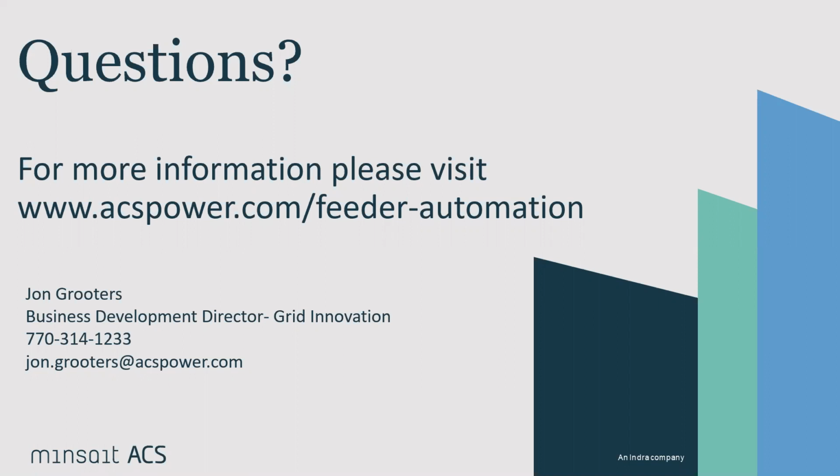So if at a later point you want to add or remove sectionalizing devices on a circuit that's already automated, you simply open up the tool, make the changes in the tool that John showed to either remove the device or add a device, select the specific type of control for that device location, export that model and re-import it to the system, and you're up and running again.